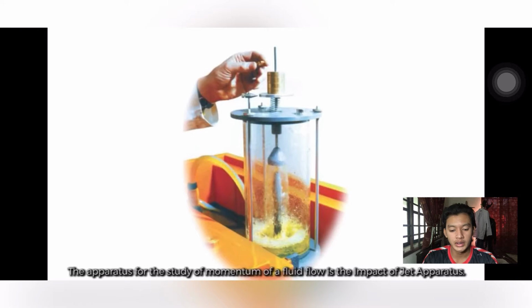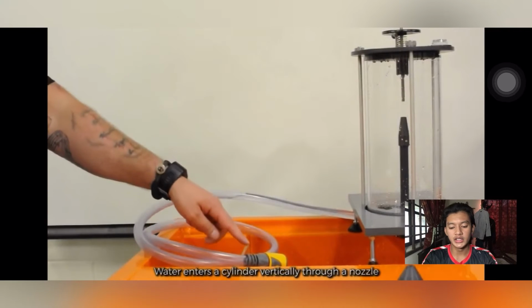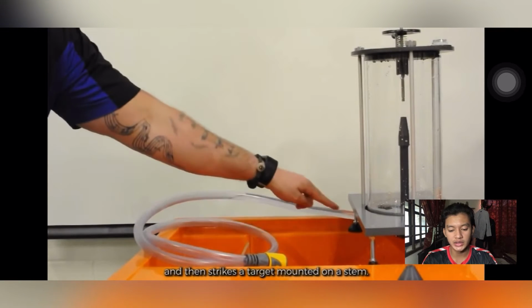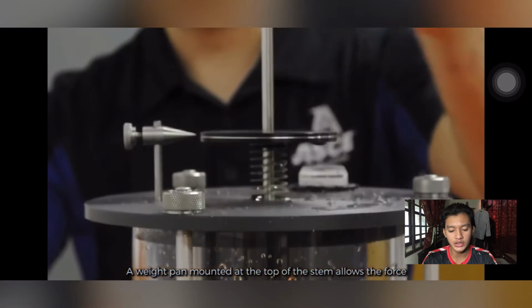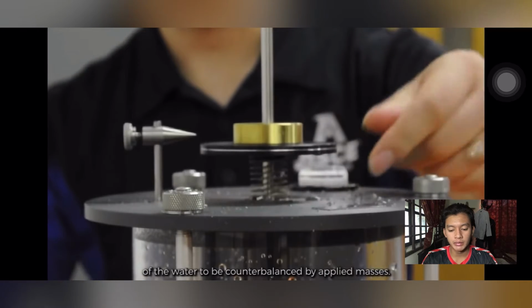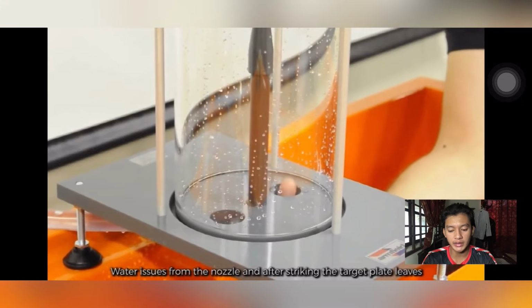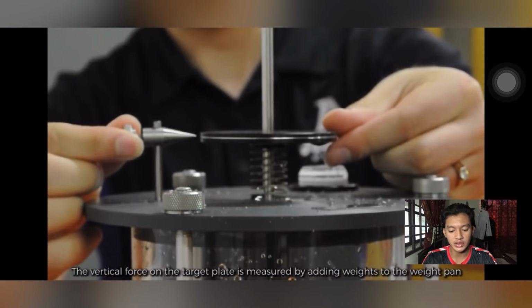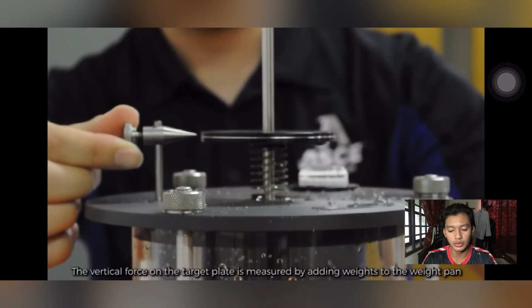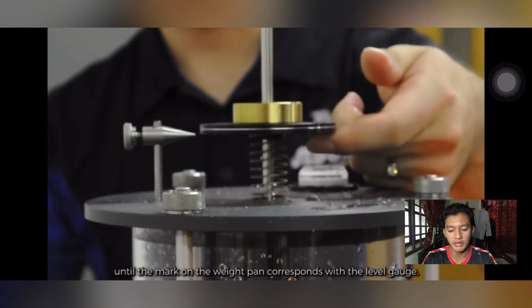The apparatus for the study of momentum of a fluid flow is the impact of jet apparatus. Water enters a cylinder vertically through the nozzle and then strikes a target mounted on a stem. A weight pan mounted at the top of the stem allows the force of the water to be counterbalanced by applied mass. Water issues from the nozzle and after striking the target plate leaves through the outlet hole in the base of the cylinder. The vertical force on the target plate is measured by adding weight to the weight pan until the mark of the weight pan corresponds with the level gauge.